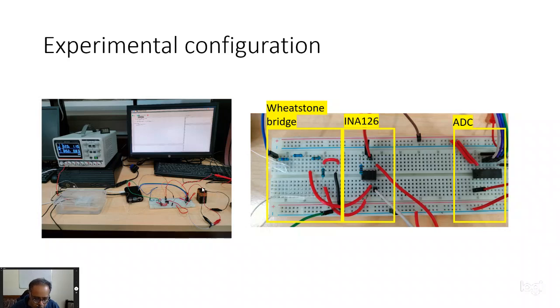The other thing is, because we are using two batteries in series, you have a common pin. That common pin is also attached to the common ground of the Raspberry Pi. This is to ensure that all voltages are measured with reference to the same voltage. So you are not leaving any grounds floating, you are just connecting it to the ground of the Raspberry Pi, which is in addition connected to the earth ground. Alright.